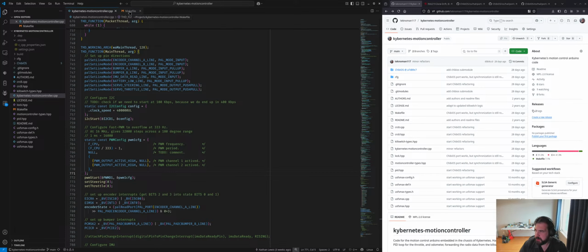So what we did was I reverted from using something called tickless mode back to the standard tick mode. The major difference between the two is that in standard tick mode, there's basically a timer that fires on a fixed interval, let's say 1 millisecond. I can't remember if it's 1 or 10 milliseconds in ChibiOS. But by default, it'll have this timer that fires on a specific interval to do any of the RTOS kernel functions, switching tasks, running timers, etc.